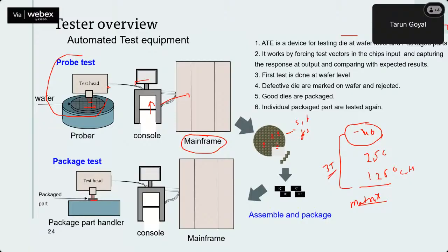These are industry levels, depending on what kind of products we are designing. In a CPU, we may have level 2, level 3. If a die is defective, okay, it's a phone, suppose we are not using it, it's not killing anyone. But when we go to level 4, we need much more quality and fewer DPPMs, to ensure we are not having more defective dies, which we call 0 DPPMs. And level 5 is more absolute, it's DPB, which we talk about in these levels.